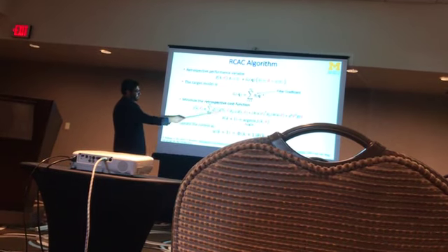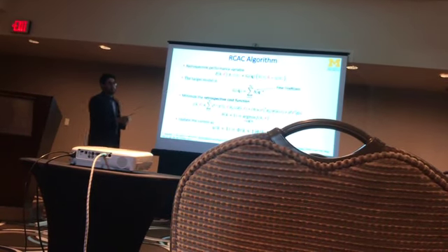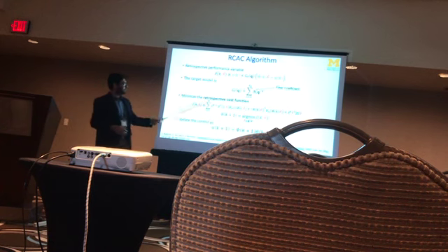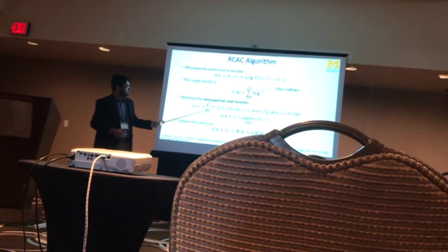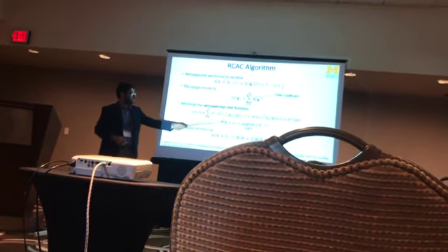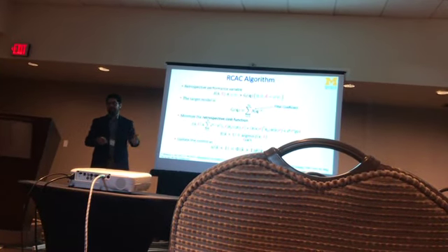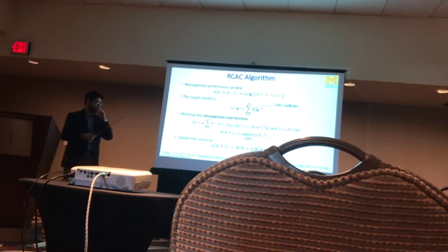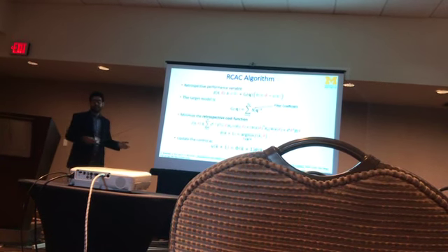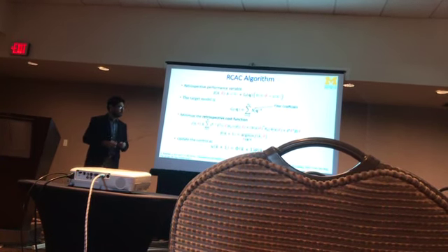this retrospective cost function, which is basically a quadratic convex function in theta hat. So this is like z hat square, and that's phi theta square. All these terms have theta squares, theta, and a constant. So that's basically a quadratic convex function. It's very easy to minimize. We use RLS to minimize this cost function.